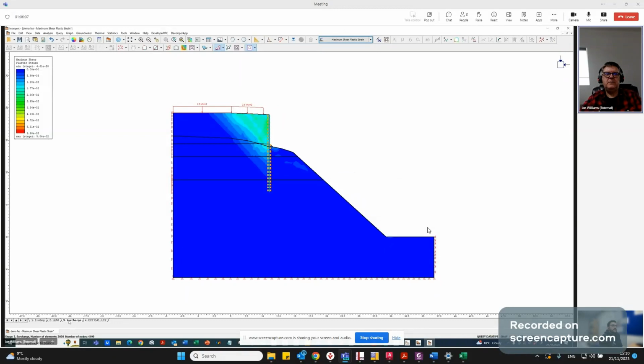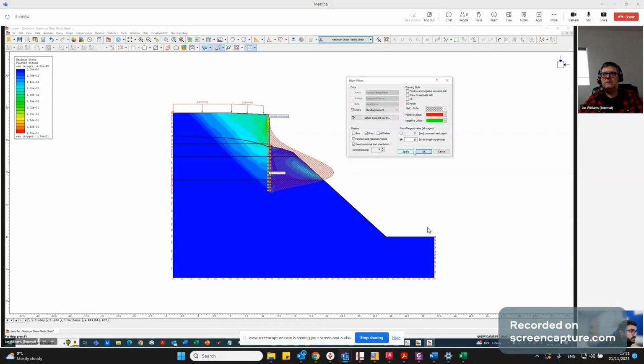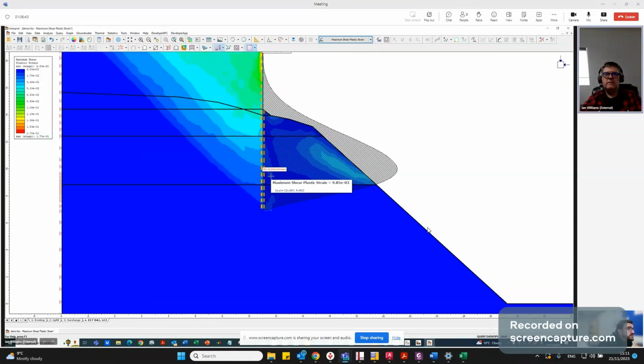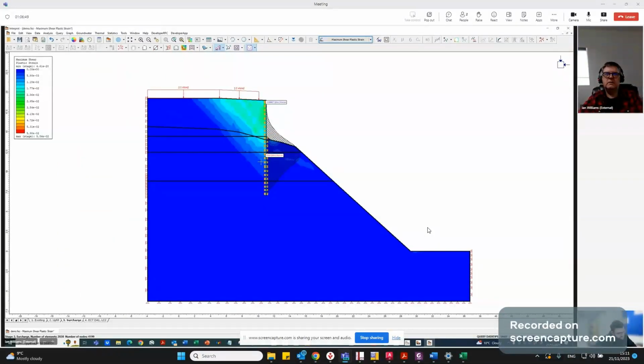At the working loads, it's not happening. But once you apply the Eurocode 7 factors, then you trigger this instability here. Perfect. So then, did you say there's no case working? Again, if you were to look at your bending moment diagram, quite a lot. 300. That's 352. That's with the Eurocode 7 factors applied, but the working load, 150.